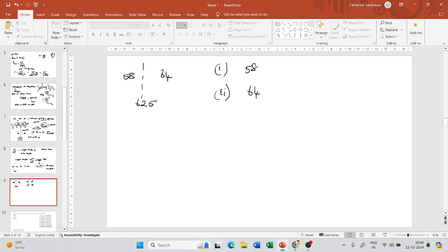Now let us check with 64 degrees Celsius, because this is the criteria that we gave for intermediate PG grade: the next highest temperature after the pass fail temperature. Let us first check if this works for high temperature. I'm going to give the PG grade for this bitumen as PG 64, and I'm going to give this to a contractor. He's not going to check it, and he's going to believe you and use it.